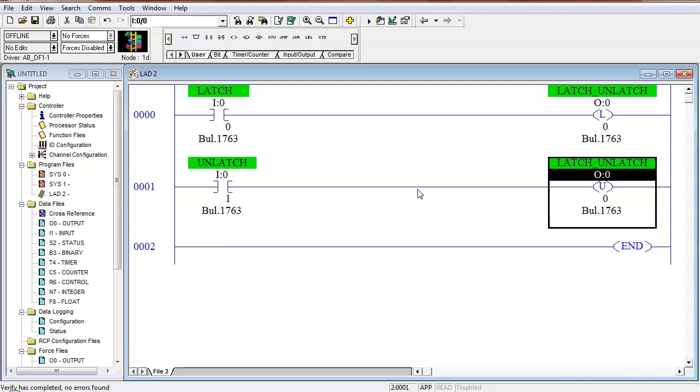Always start a new program. Because now you've got all these symbols assigned. And over here they want to call it Limit Switch 1, and you're trying to assign it, and they say, well, this thing won't take my symbol. Why? If you try to enter a symbol and it will not take it, what do you think that means? Yeah, you've used it before. So don't take a program that you're working on and try to modify it, because I might come back and want to look at your other program. Well, let's don't do that.